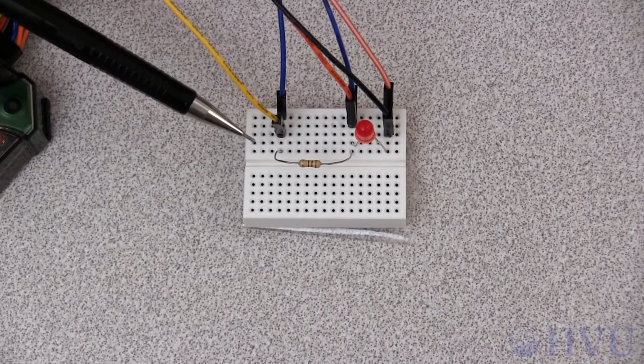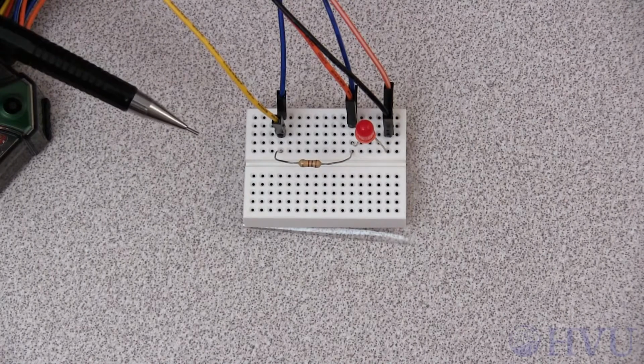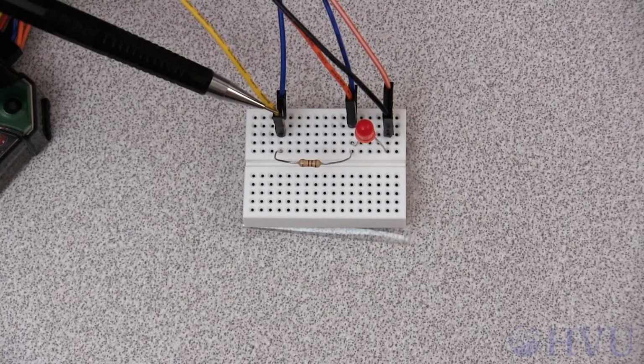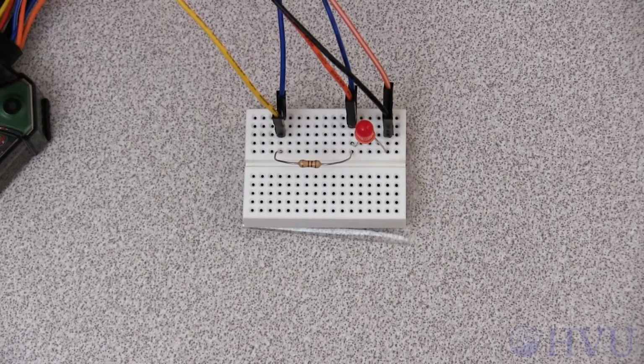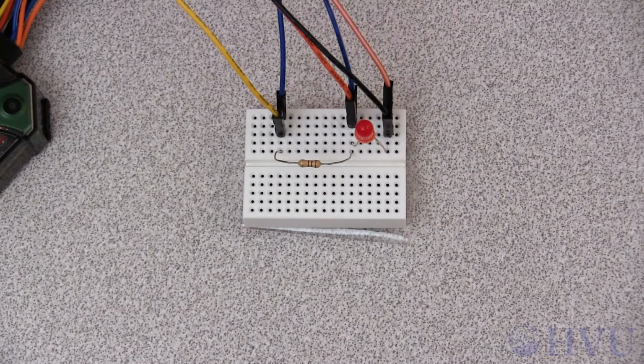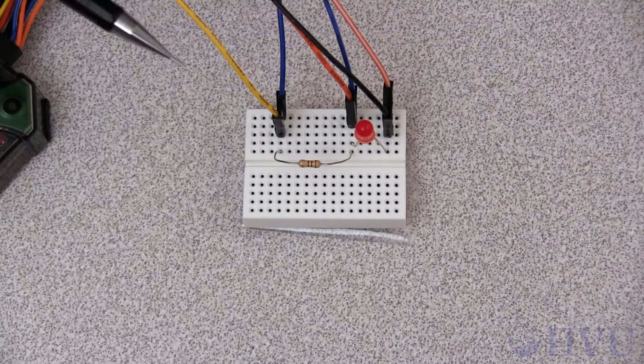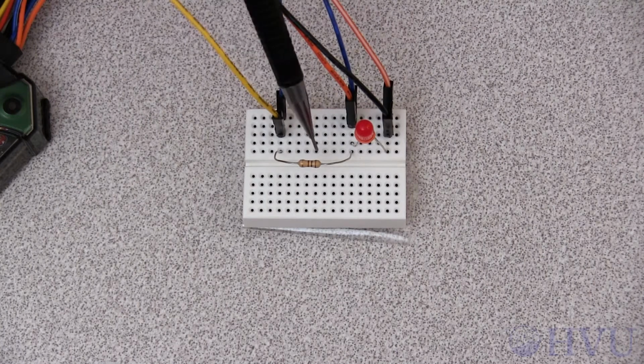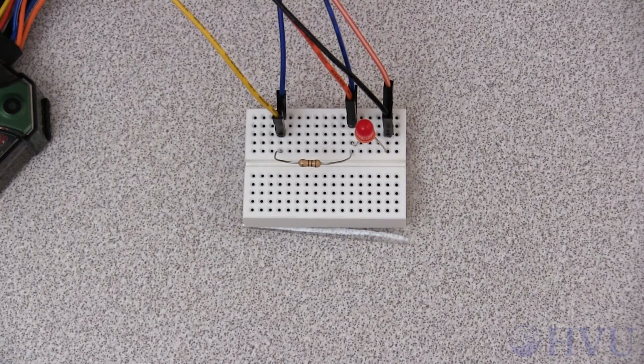This is our circuit. We'll apply a time-varying voltage with channel 1 of the waveform generator, the yellow wire. Ground is here, and we can use any black wire to make that connection. We'll use channel 1 of the oscilloscope, the 2 orange wires, to measure the voltage across the diode. And we'll use the 2 blue wires to measure the voltage across the resistor. Now we're ready to test our circuit.